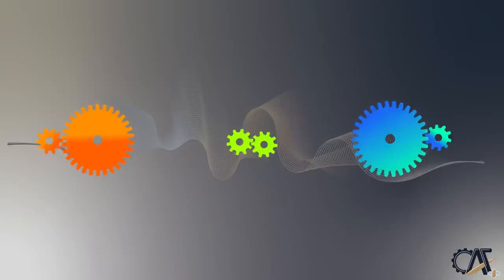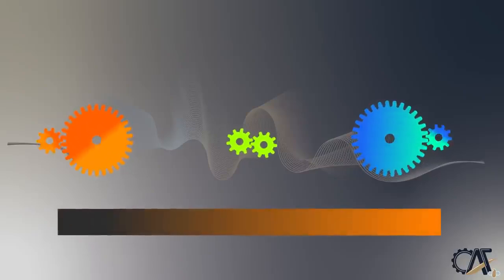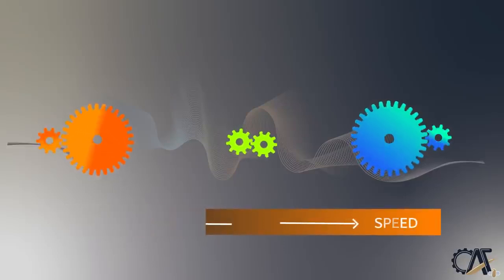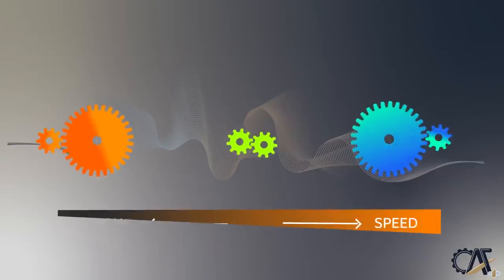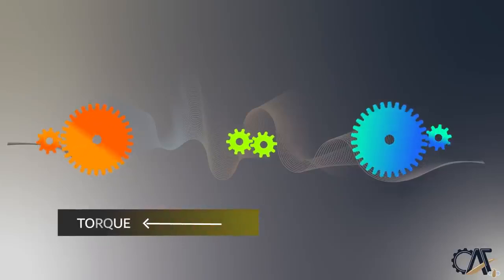So if we want to put all the 3 gear modes in one picture, we can make the following conclusion. Since the rated output power of a motor is a fixed value, speed and torque are inversely related. In the gear reduction mode shown to the left of the graph, a larger output gear is used, thus the output speed decreases and the available output torque increases proportionately.